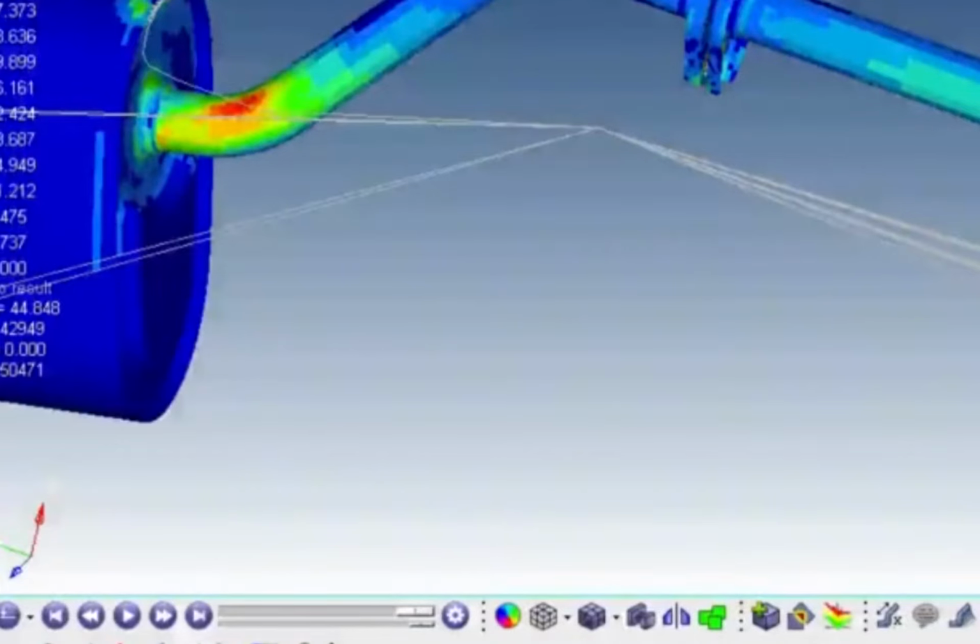So we give the user the option to output the mean value plus 5 times the RMS, or 4. He can specify the number. I put it 5, but you can make it 4. More traditionally, you'd make it 3, because 3 times the RMS corresponds with what a lot of people call Six Sigma design. Six Sigma design means plus 3 times the RMS, minus 3 times the RMS. So you can replicate that in the results sets here if you want.